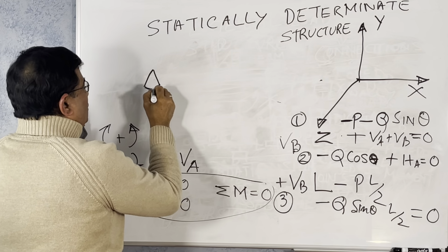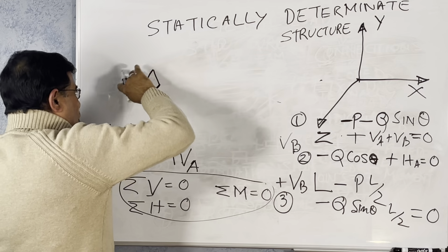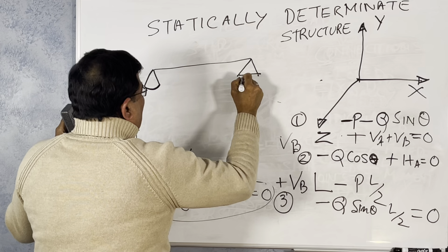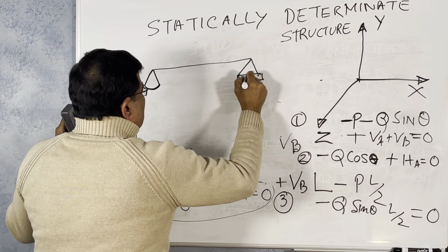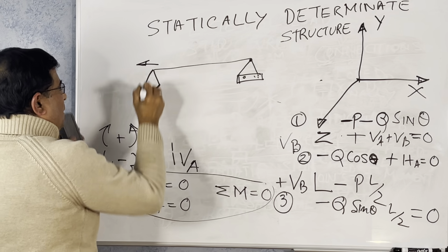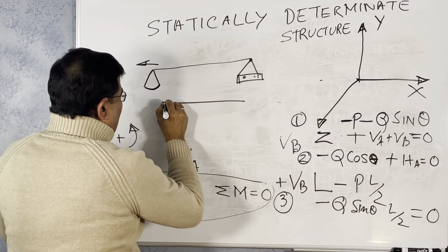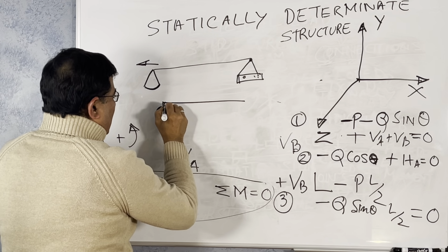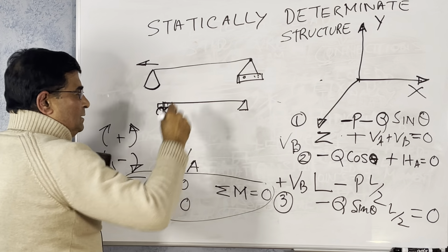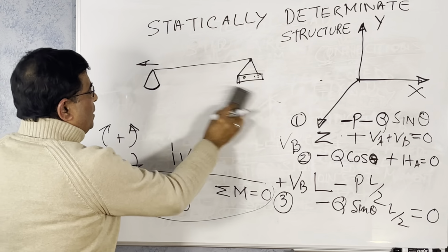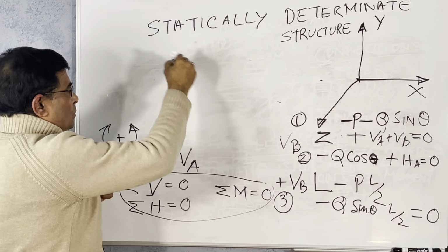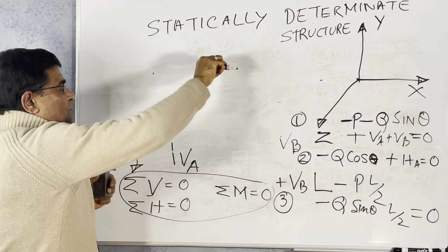They make it like this. This is your roller support. This can rock. And the other side, they make it a hinge. Roller means it can move. In some places you will find exactly the roller like that. The plate is something like this, and you have a hinge like that. Nowadays, we do not use that type of bearing. That is called a bearing. They support the places where the beams are resting.